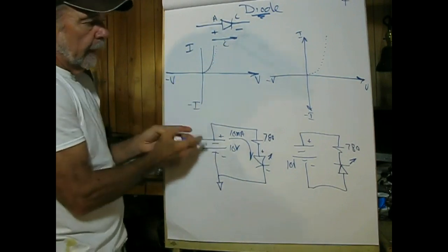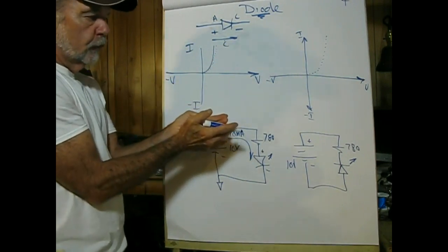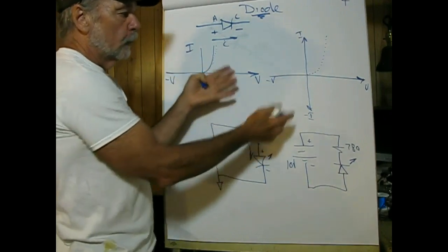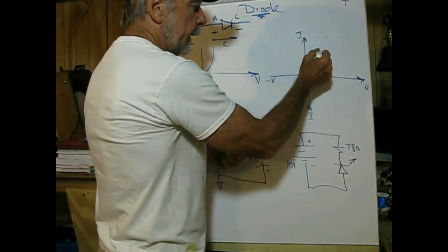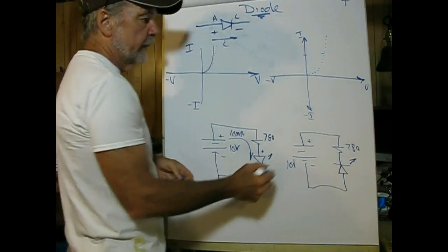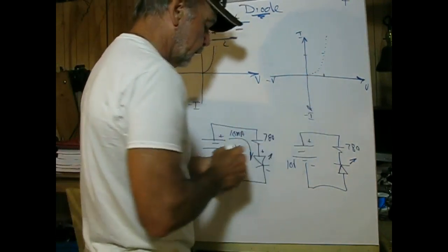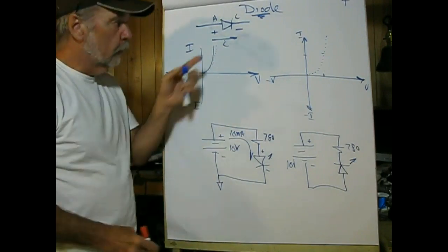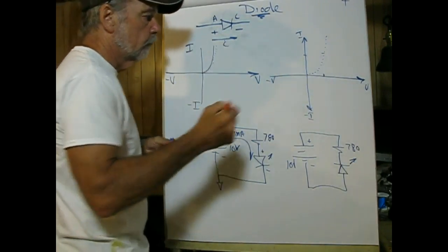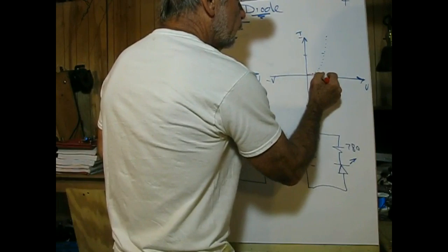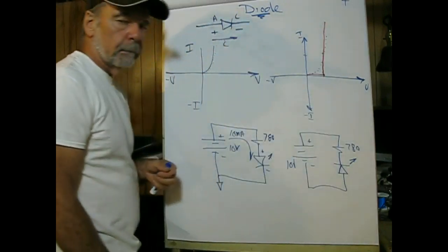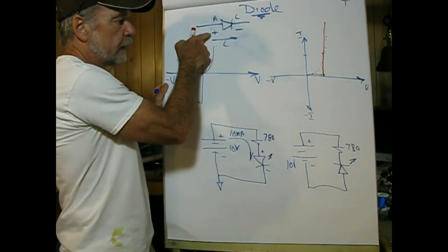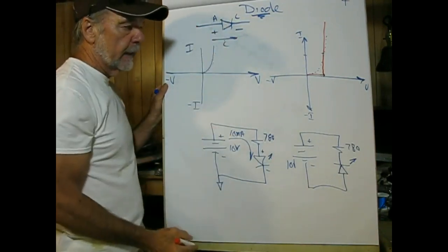So, for our purposes here, what we're going to do is use a model that approximately represents this operating at a common voltage, and what that model is going to look like is that when current is flowing, this is important, when current is flowing in this direction, the characteristics look like this. Simple enough. So this is when the anode is positive with respect to the cathode.